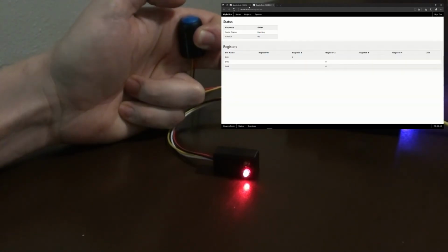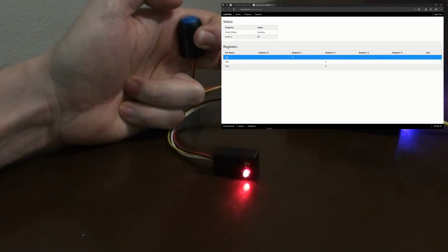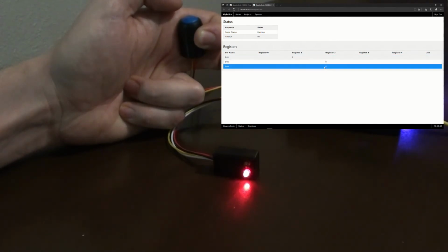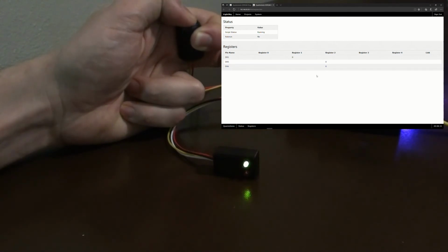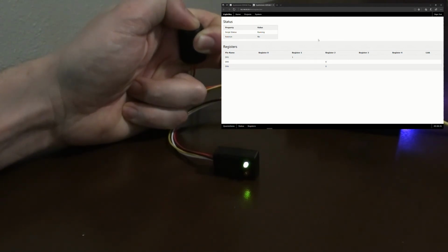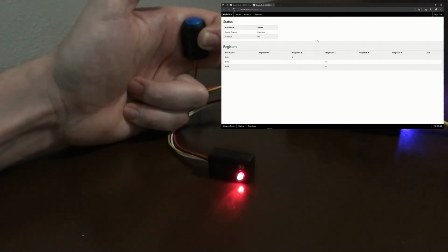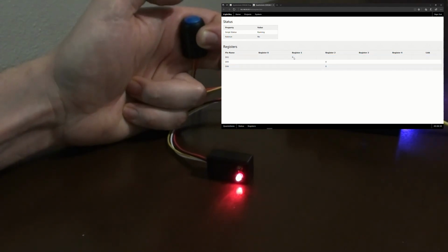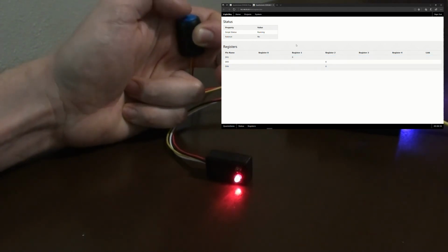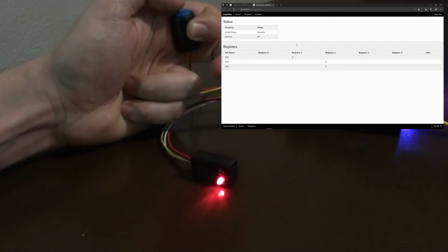If you go over to the scripting page again, you'll see that we've got the input pin as D1, and D5 and D6 obviously are the two LEDs. Now you can see that they're all in 0 state. Whereas if I press the button, that one reads 1. Just refresh. And if I release it, it goes back to 0. This is just to show you the delay in the HTML page getting the instruction from the microcontroller versus the responsiveness of the script running in the background.